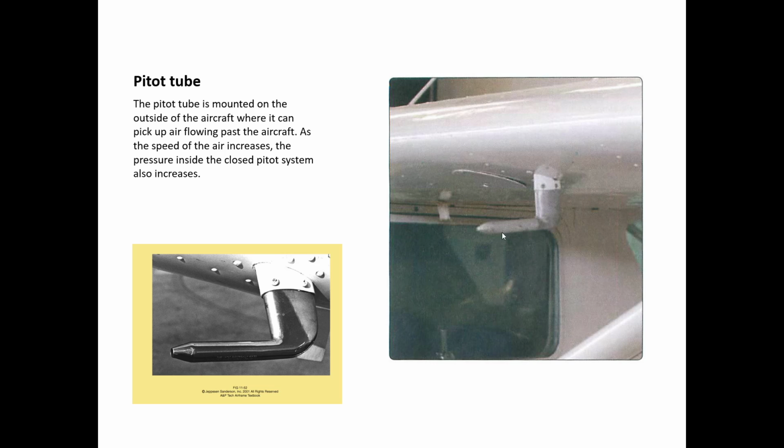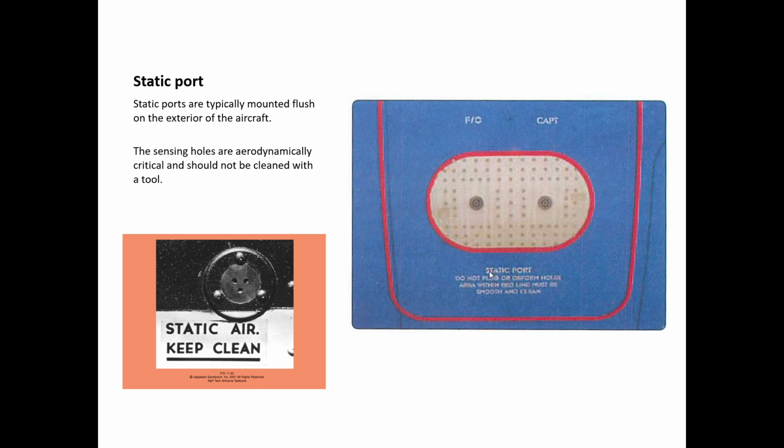Then there's going to be maintenance also in the pitot tubes, as the little bugs like getting in there to make their nests, little mud flies. Usually you clean them with compressed air, if you're able to without disrupting the instruments. You wouldn't want to blow it right in here because they're connected by tubes to your instruments.